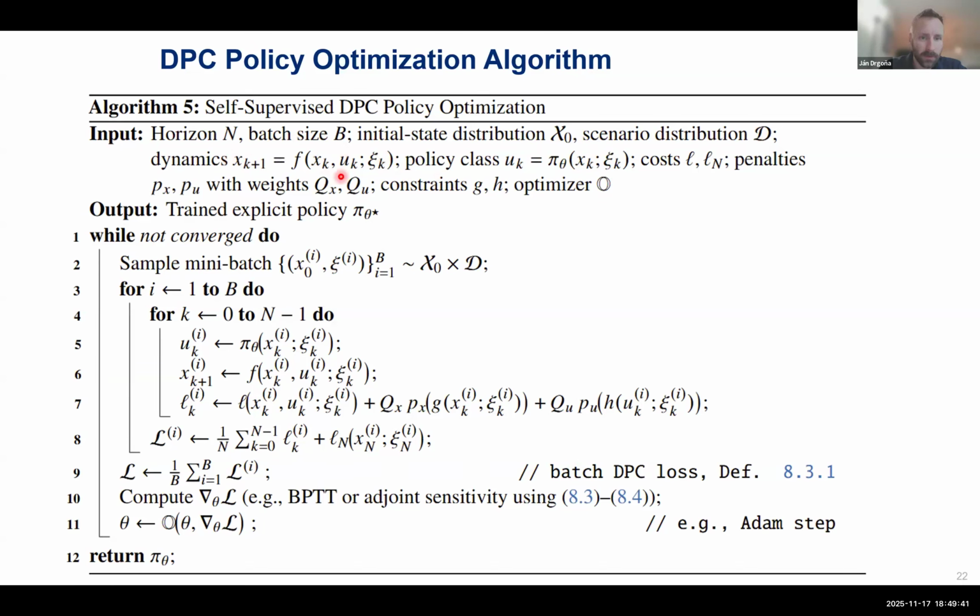You need to have the dynamical system model, either state space or differential equation that is differentiable almost everywhere, and you have some control policy representation. Typically, we are using deep neural networks, but this can be really any differentiable representation like polynomial basis functions. And what we are doing in training is selecting the mini batches. So it's basically B number of samples from our overall training data.